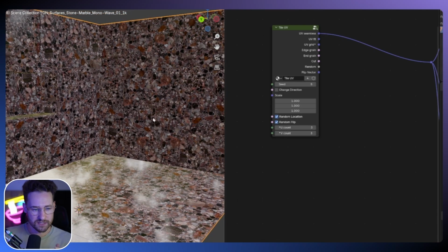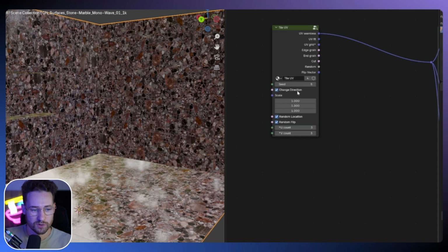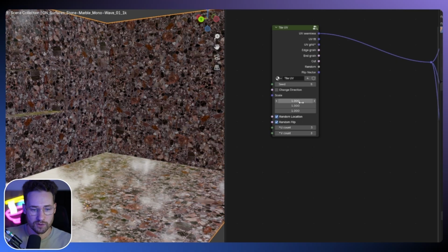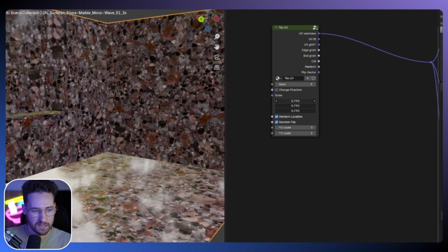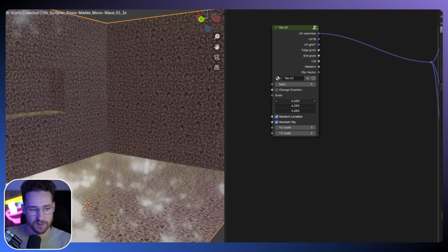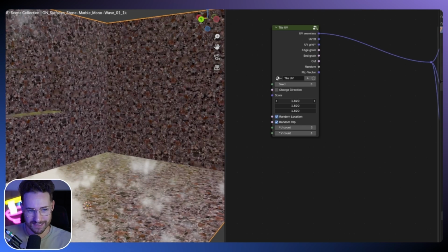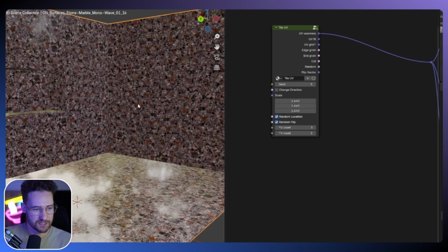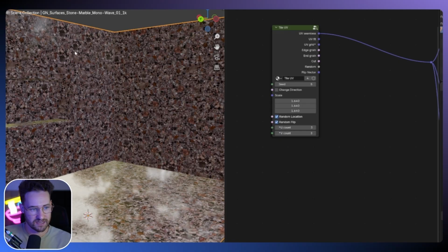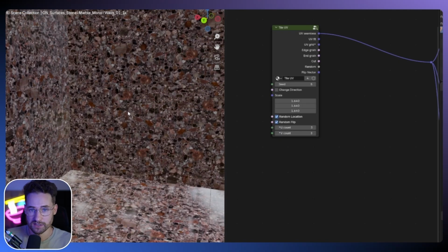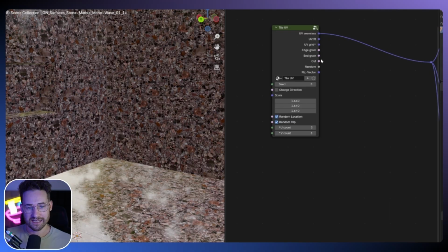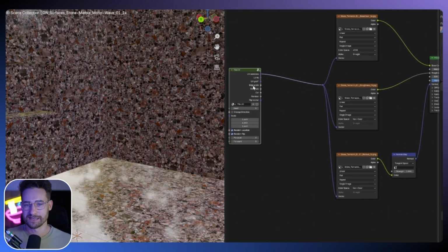Now, flipping doesn't always work quite nicely, because sometimes if a tile is side by side and the other one's flipped, then you'll see a mirror, but this works in quite a lot of cases. You could also change the direction if you wanted to, but this works amazingly well. We can also change the scale of these. And as it's seamless, we can go right out, but then we start getting the same problem with the seamless texture. But with something like this, there's no longer any tiling, and this looks amazing. Obviously there's some repetition, but to me this looks like a randomized object. So in that case, where you just have one set of textures, UV seamless is amazing.